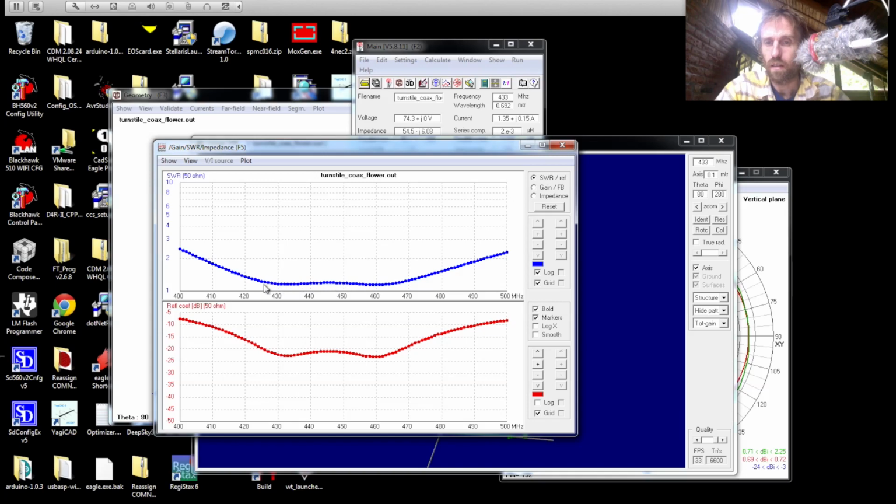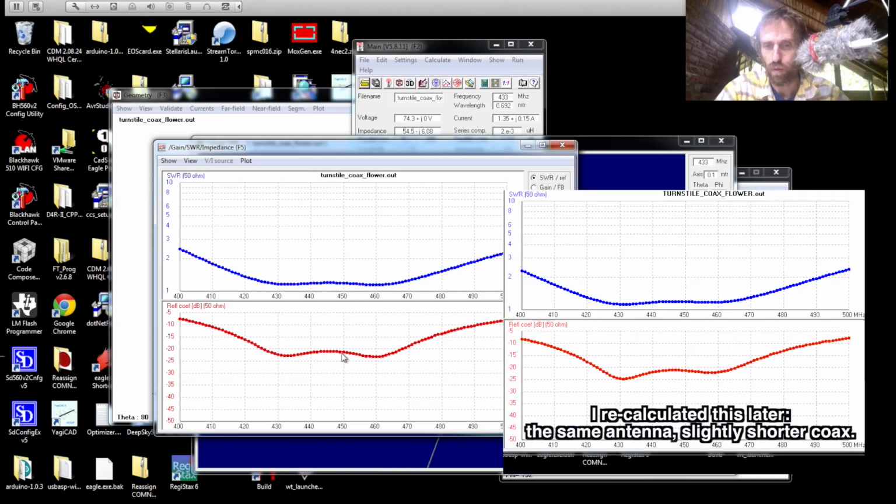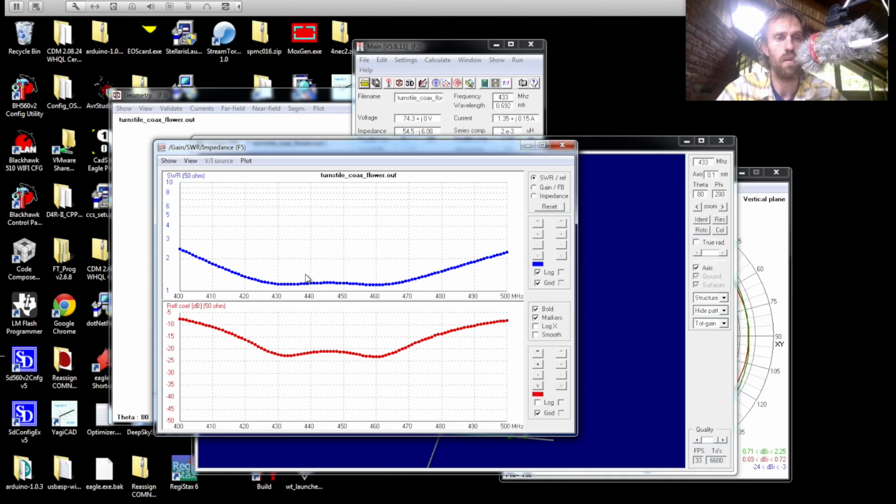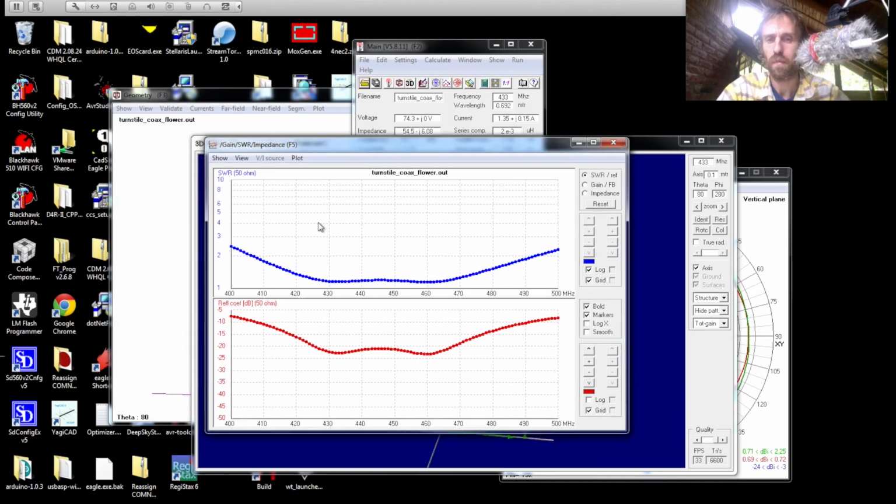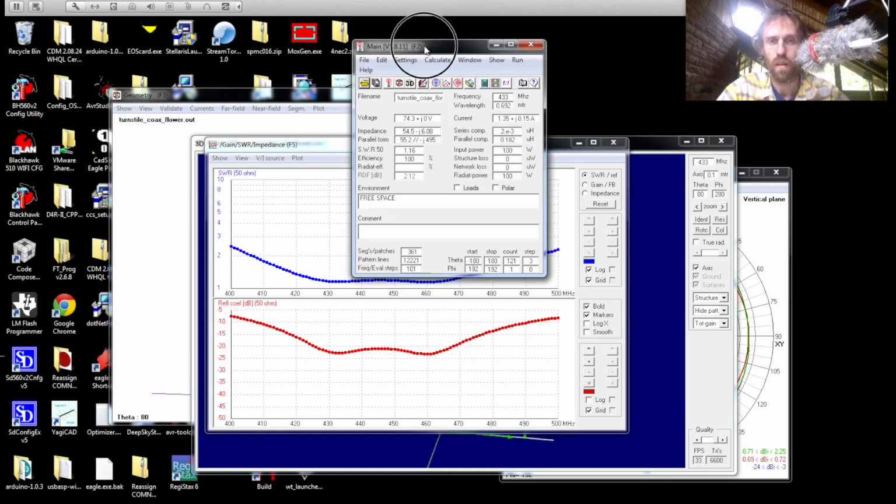Anywhere in between that, the results are pretty good. The reflection coefficient goes up a little bit here, so you are going to get slightly worse here, but you could also hop across these frequencies as well, and this style of antenna will work quite well. You've got to think also the performance of your other antenna at the other end, whether it's a V antenna or your moxon antenna, and see what your actual performance here is like.